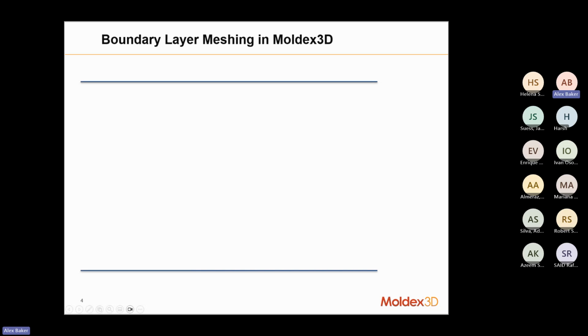What we just did is we created the node seeding, which is used to define the surface mesh. The nodes that are created across our geometry are also going to be used to create the solid mesh through the thickness. That's what we're looking at here, the top surface and the bottom surface. You can consider it, we're looking through the thickness of our geometry. Each of those surfaces, the top surface and the bottom surface, has their own node seeding applied to them.